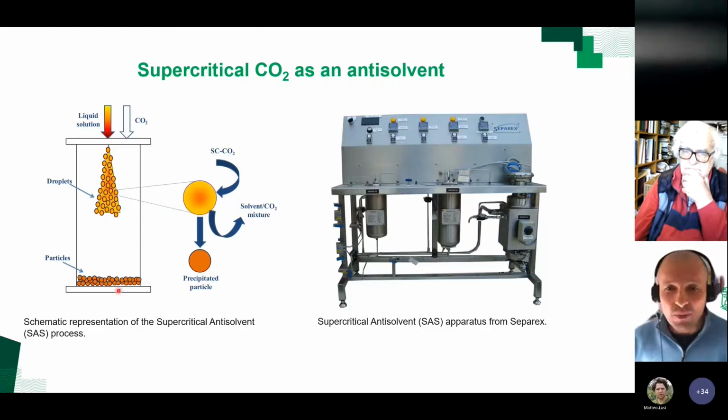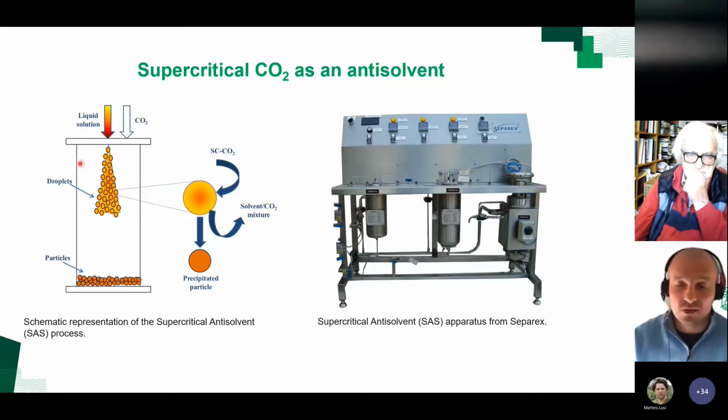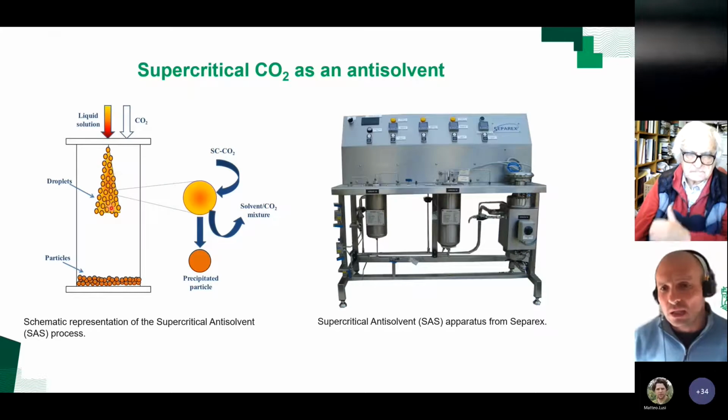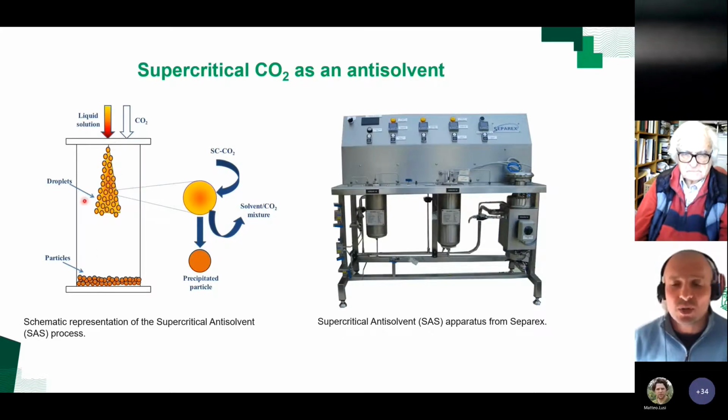But this is all under high pressure. So if we need to scale this up from lab scale to pilot scale to industrial scale, it's very complicated. It's complicated to maintain the homogeneity of the droplets, the size of the droplets, and the homogeneity of the CO2 dispersed in the chamber. And obviously, the larger the chamber, the larger the high pressure vessel, the more challenges and the more risks it imposes in regards to safety concerns.